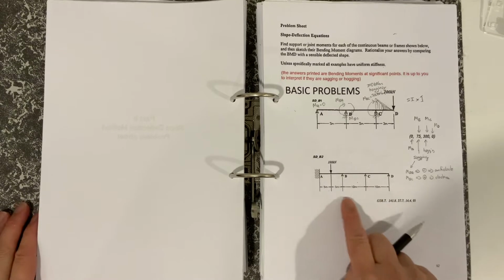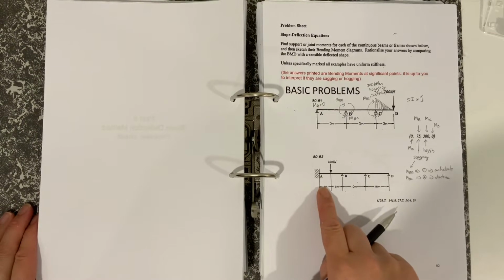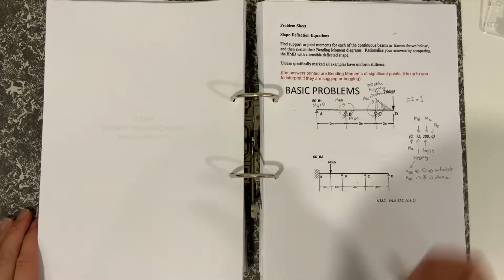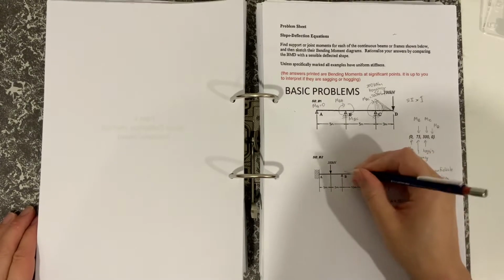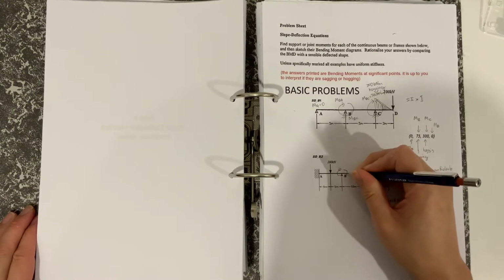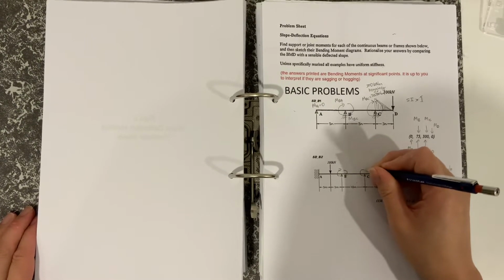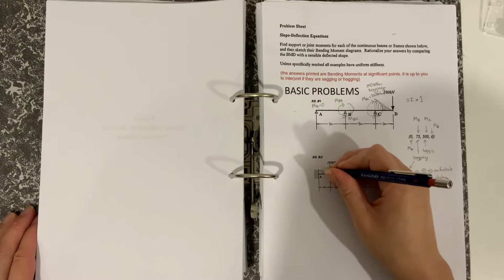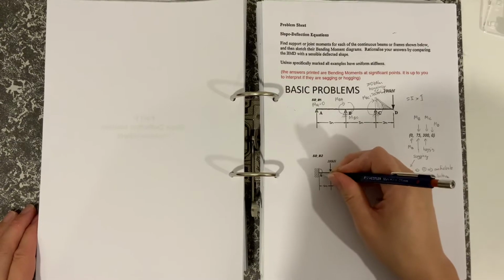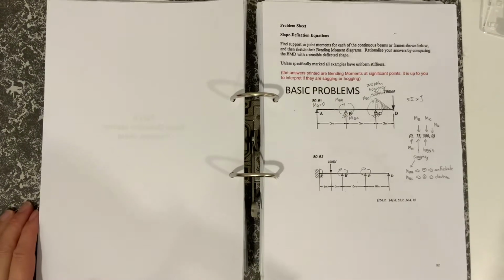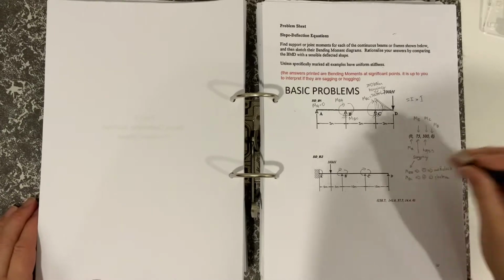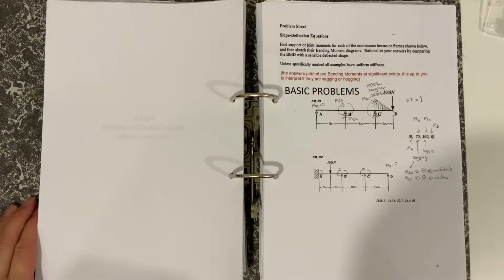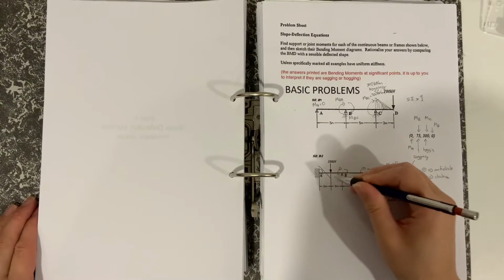This one here is a similar problem to what we've seen before. When you do the slope deflection calculation, the first thing to do is to put everything in as clockwise. So you would be putting in the arrows here in the clockwise direction, because you don't know what they are, and you would be using the slope deflection method to help you calculate it. So everything is drawn in the clockwise direction, and you would be able to deduce that MD would be equal to 0. So the bending moment diagram would probably look something like that.